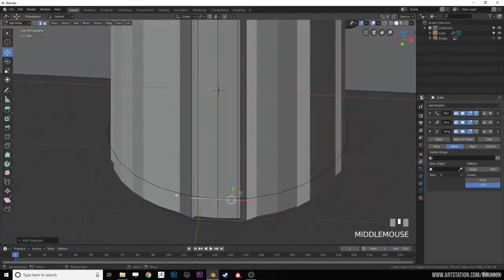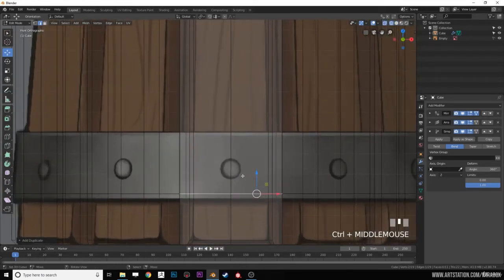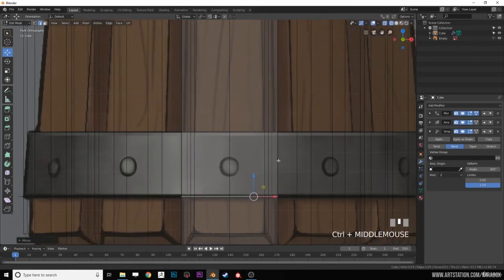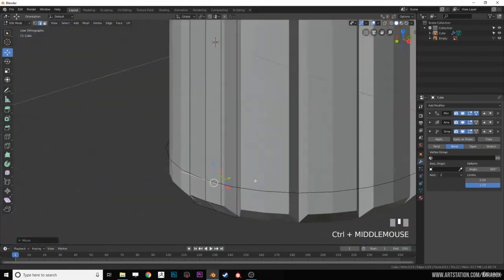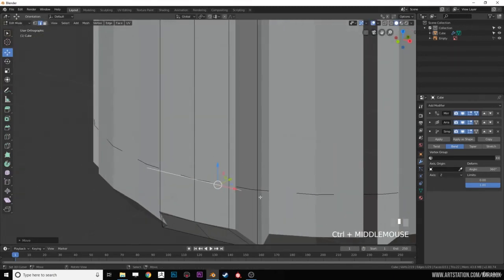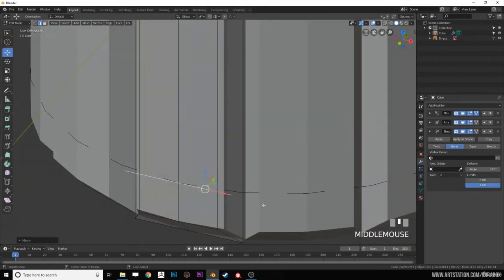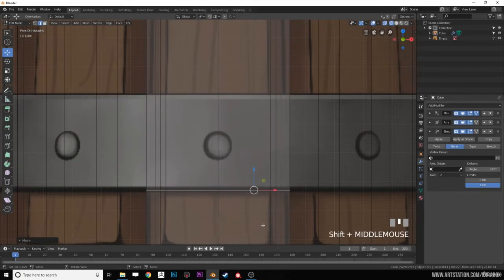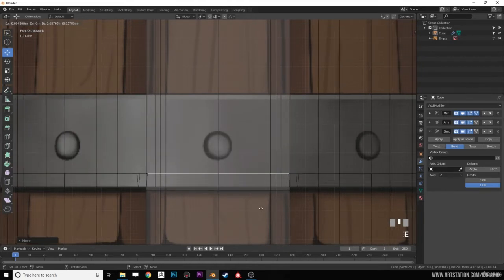In this way we can see that it creates a circle around the wall mug, and we are going to place it in the lower edge of the metal ring that we have in the reference. Also here we can move it a little towards the center in a way that it can penetrate the mesh a little bit, as it is here. Okay, let's extrude this up again in the Z-axis until the edge that indicates the reference.